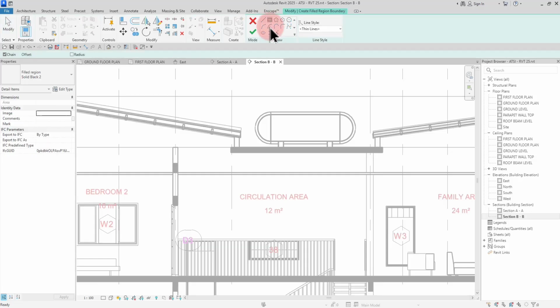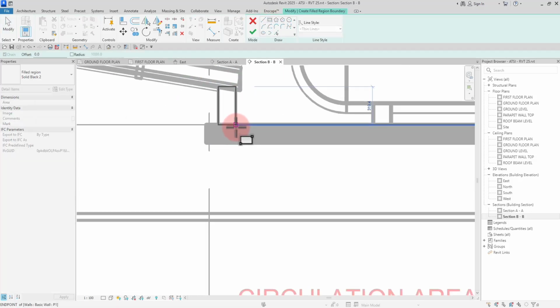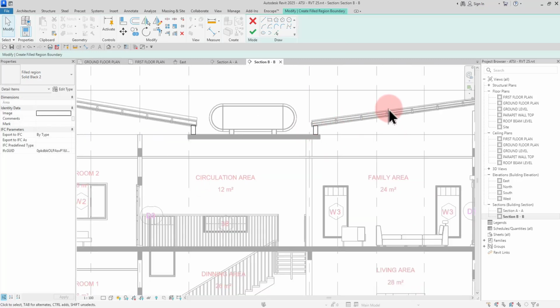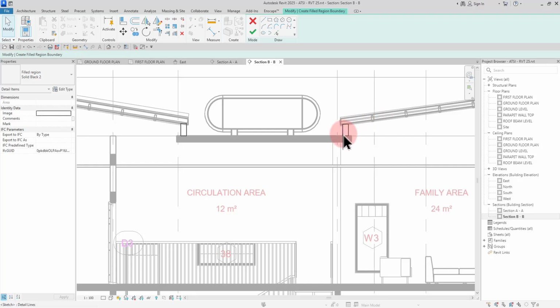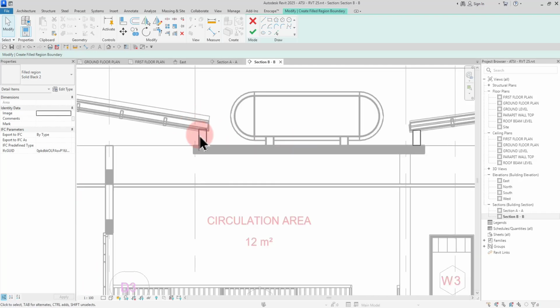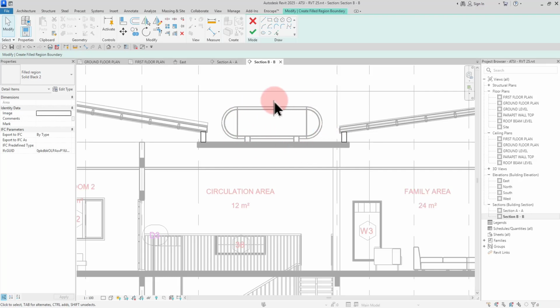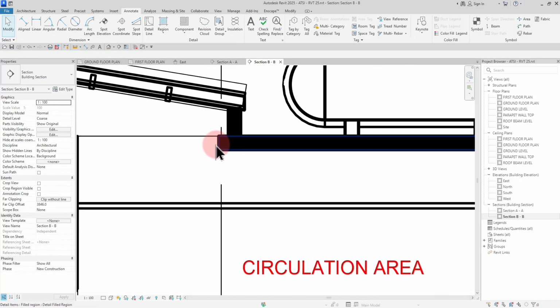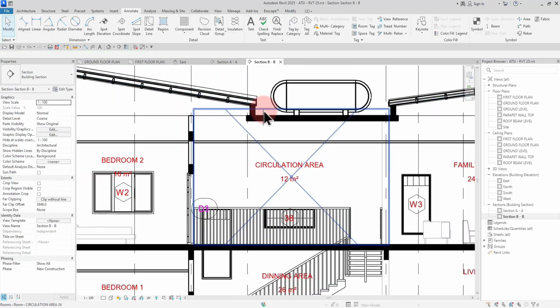And you have to do the same solid black as well for all those block work all coming up. So this block work is to be able to collect water from this inclined roof, all the water dropping in this area. So if we should put the roof exactly on the floor slab, the water is going to seep under there and head into the building. So you need a block wall of about 450 going up, which is going to preserve the water in that area, and then it's going to be collected by a floor drain outside there. All right, so we just have to take that and make that black as well. So we are good to go.